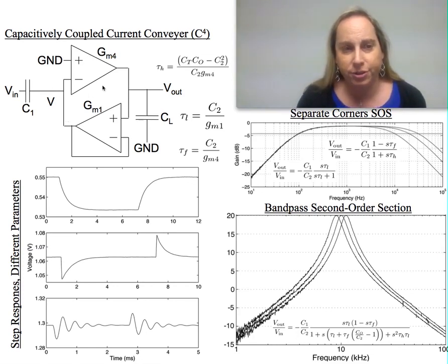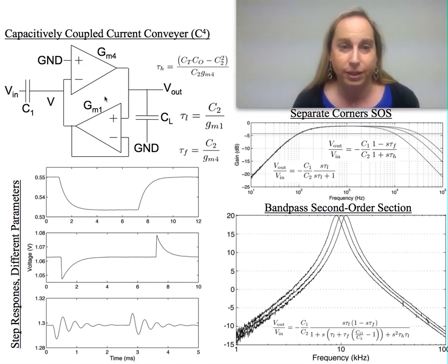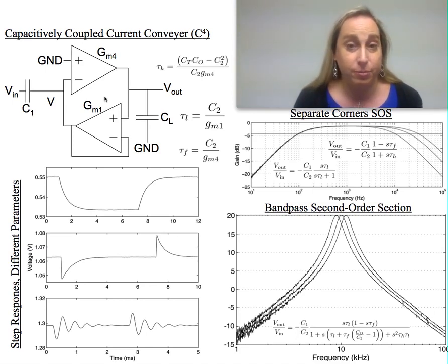What's nice in these structures is that you're typically talking about having this set to two, and having a signal ground here. This would typically set the reference voltage for your structure. We're going to have two transconductances that are set, whether this is above or subthreshold. In subthreshold, these are pretty well understood structures and variables. The OTAs themselves could also have floating gates as the inputs, or other means to have a wide linear range. So often we'll want to talk about the transconductance in somewhat more general terms, depending on the particular family and types of circuits you're working with.